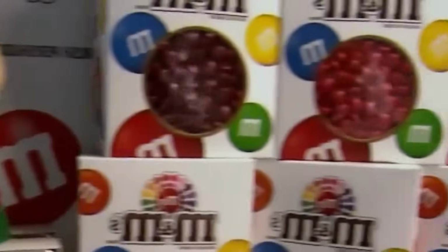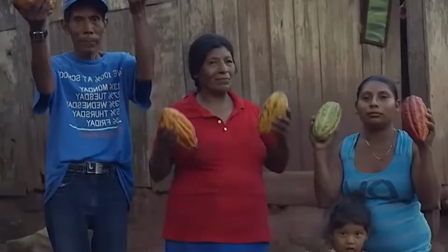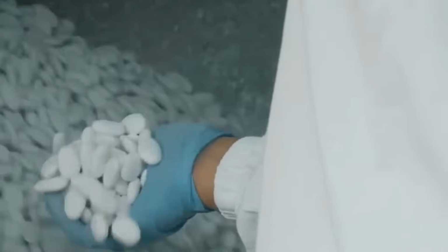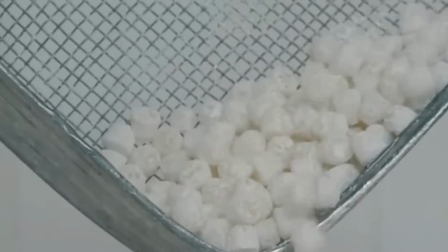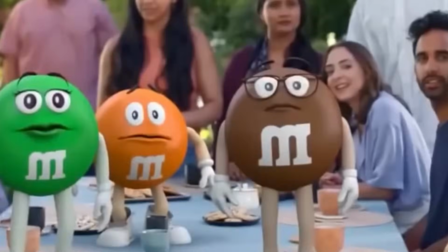Shelf life studies are conducted on retained samples stored at standard and accelerated aging conditions. Cleaning and sanitization are conducted on a rotating schedule. Chocolate and caramel handling areas undergo full CIP clean-in-place procedures involving hot alkaline solutions, acid rinses, and sterile water flushes. Sugar panning and polishing pans are dry cleaned using brushes, vacuum systems, and compressed air. Contact surfaces are swabbed for microbial residues, and test results are logged digitally for traceability.